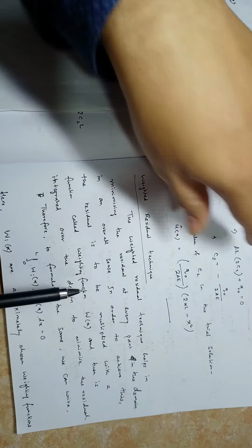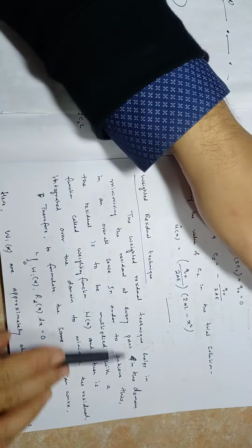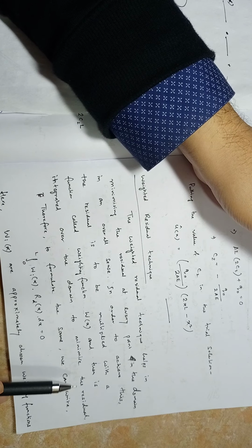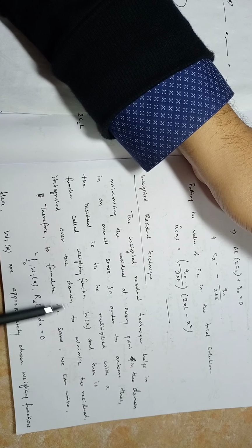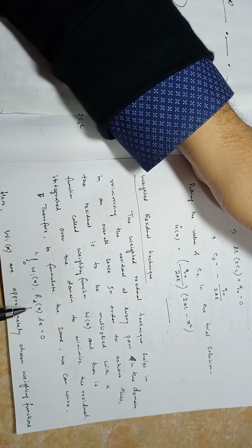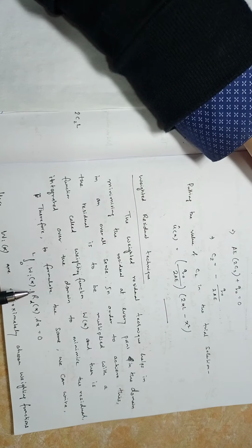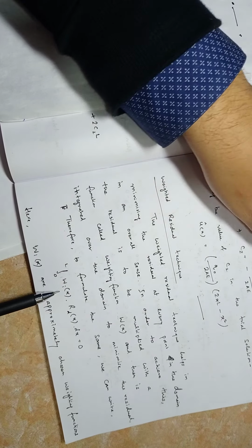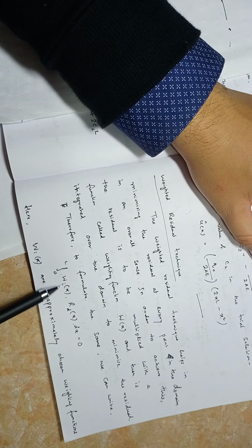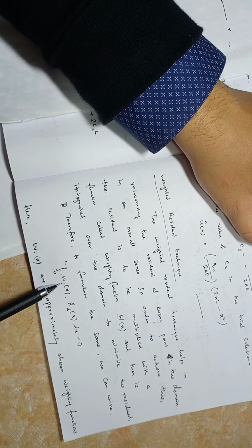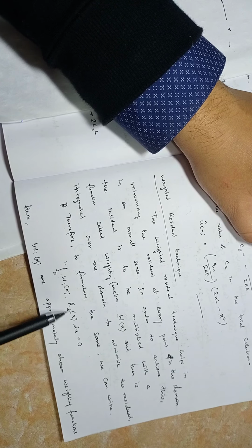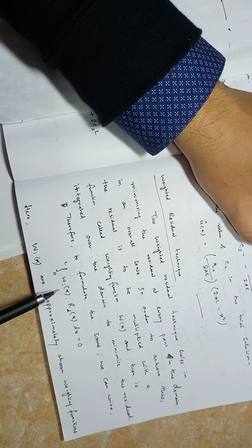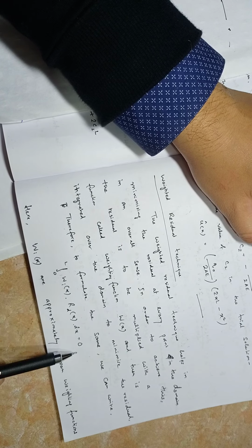Okay, so here it is written, the weighted residual technique helps in minimizing residual at every point of the domain in an overall sense. So in order to achieve this, we multiply by the weighting function W(x) and then integrate it over the domain to minimize the residual. So this is what we do. Residual is there, residual will not change, but we have to multiply functions, that is called weighting functions. There may be one, so W1 is one weighting function, W2 will be another weighting function, so there will be more than one integral equation.